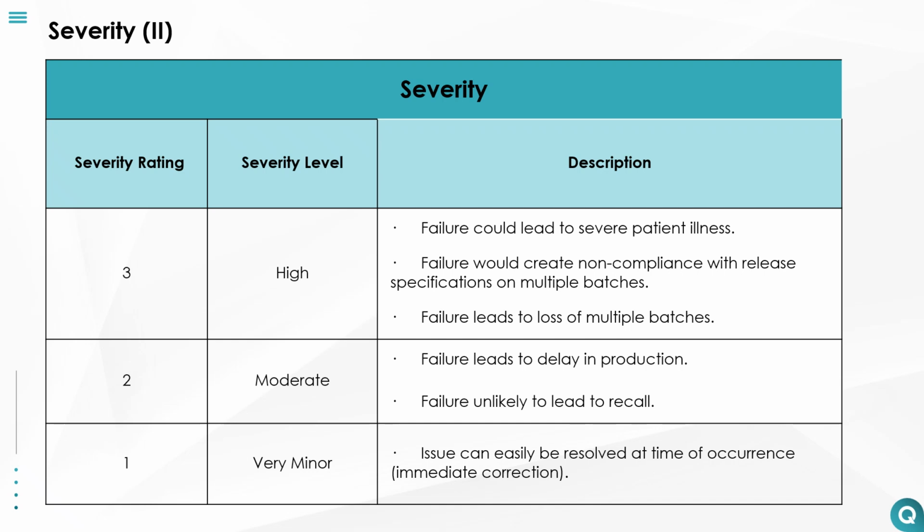A severity rating of 2 would include something such as a failure of a labeling machine, leading to some vials being labeled with smudged batch numbers that were in some instances difficult to read. This issue was identified during QC checks before the batch is released. The affected vials would need to be relabeled, causing a temporary delay in release of the batch. However, there is no impact on the efficacy or safety of the drug itself. The inconvenience and potential minor delays in production or release would warrant a severity rating of 2. If there had been an incorrect drug or concentration labeled, this would be a very serious incident, potentially requiring a